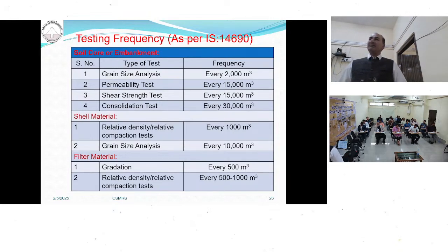But if you go to the river bed, by seeing the soil, you can, by conducting a test, say okay, this is my loose strata and so on. The relative density is also determined in the laboratory. There is a particular machine in which you provide vibration to the sands. Because this is sand, it is a non-cohesive soil. So by the vibration, it gets compacted. So you determine the maximum relative density of that material.